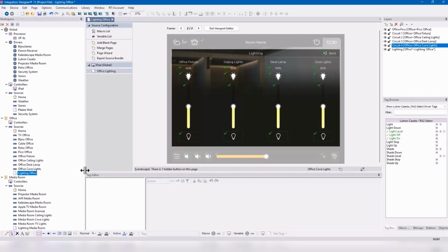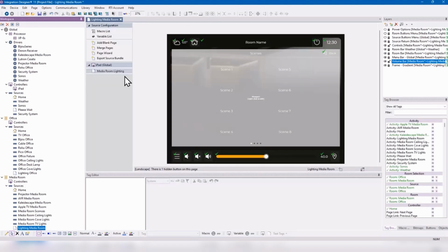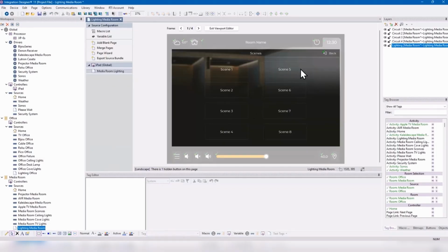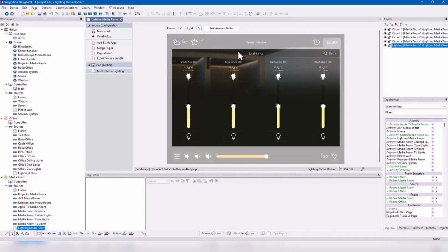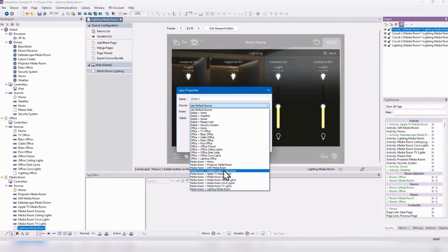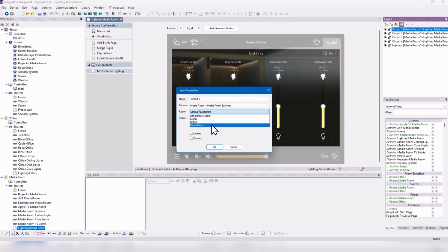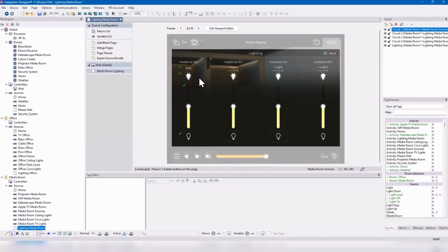And of course, you're going to go to the media room and do the same thing again. The media room doesn't have a Pico, so you could just program some phantom buttons, and we've created phantom buttons specifically for the media room, like movie and stuff like that. So again, same thing you're going to do. You're just going to program your scenes and link your dimmers to the room devices. So I'm going to aim this at the media room sconces. And it doesn't matter what order you go in. And now that's programmed. The only thing you have to do again is name the dimmer.